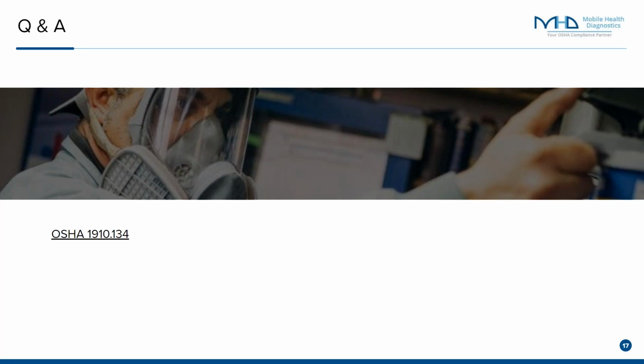Perfect. Okay. The next question is, what is your experience with conducting quantitative fit tests on filtering face respirators? My experience is the tubing may cause the respirator to drop and cause failure. Yeah, that's a good question. Inherently, an N95 respirator, whether you're doing qualitative or quantitative, is going to be generally more challenging, because while it is a tight fitting, and I use that in air quotes, respirator, the straps are much less robust than what would be found on an elastomeric, half face, or full face respirator.